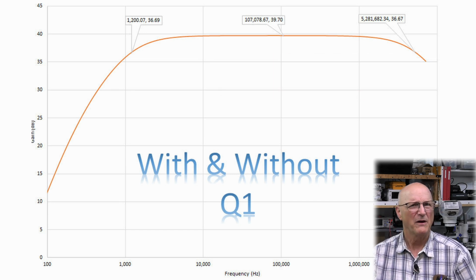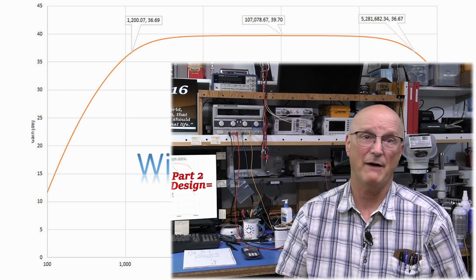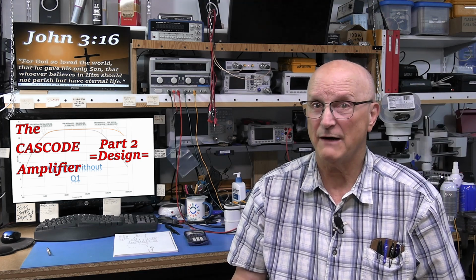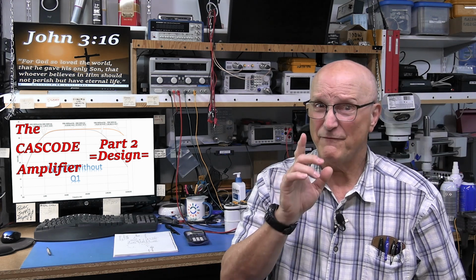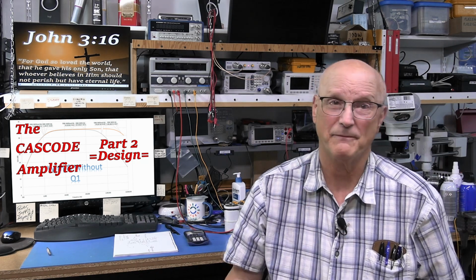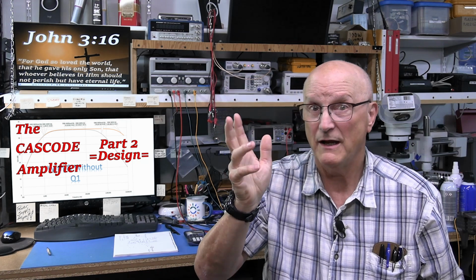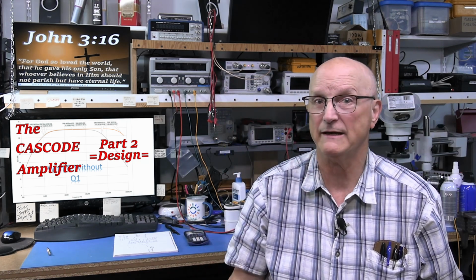But, you ask, what is the advantage of this over the much simpler common emitter circuit? Well, to see this, I have to set up the simulation without the common base part of the circuit. But I have to be very careful here not to disturb the operating conditions of the common emitter circuit. The temptation would be to simply pop out Q1 and put a short between where Q1's collector and emitter were connected.